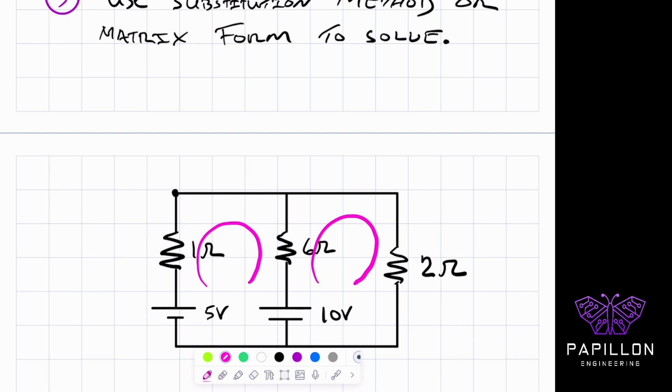Traditionally, as I mentioned before, if it leaves the positive end, we generally expect that the current in this first loop on the left will be going clockwise. And again, because this is the negative side, positive side, negative side of our voltage source, we could also assume that it's going to go clockwise here as well. Why? Because the current generally leaves the positive side.